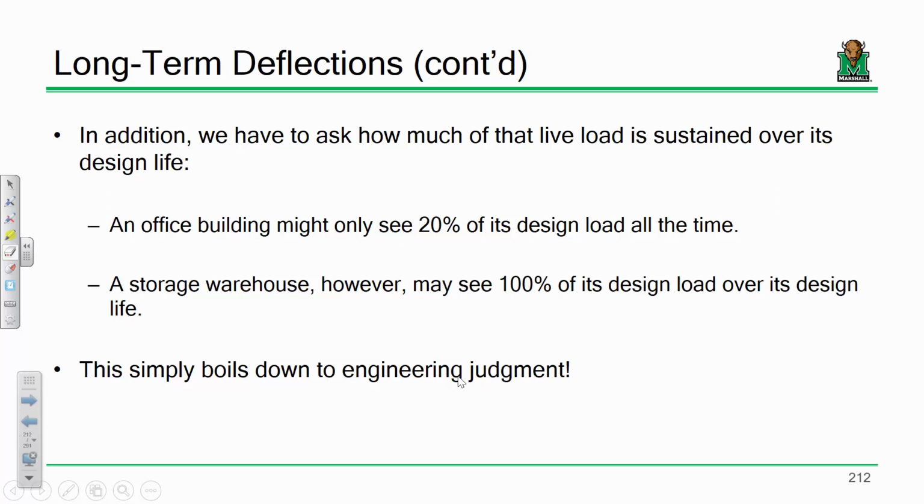But one other question we have to ask is about how much of that load is sustained. I would argue that for a storage facility, a warehouse, a library, something like that, anywhere from 80, 90 to maybe even 100% of that design load can be assumed to be sustained over its design life. And what I mean by that is that load is always there.